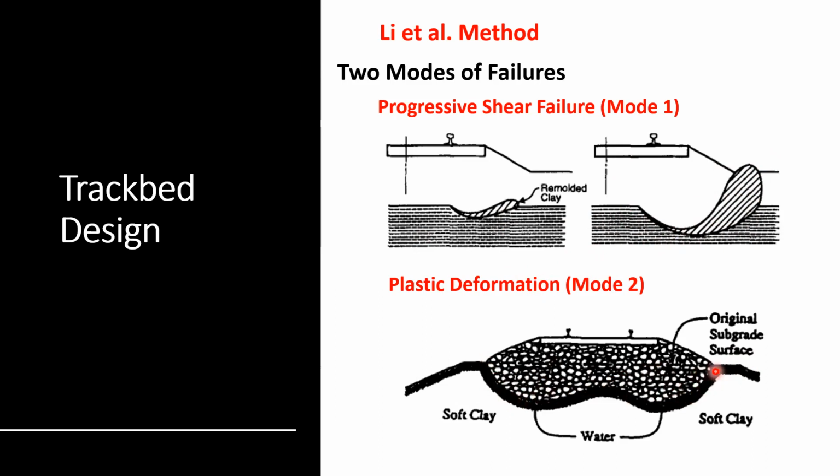As a matter of fact, sometimes when people overlook the plastic deformations along the rail track, and when they do maintenance, they keep adding more ballast into the fouled areas or the areas of deficiency or excessive settlement. And what this does is, because you've exceeded the plastic limit of your soil, you end up getting concave shapes vertically, transversely, and also longitudinally along your track. You will have a Z shape of ballast basically sinking into your sub ballast.